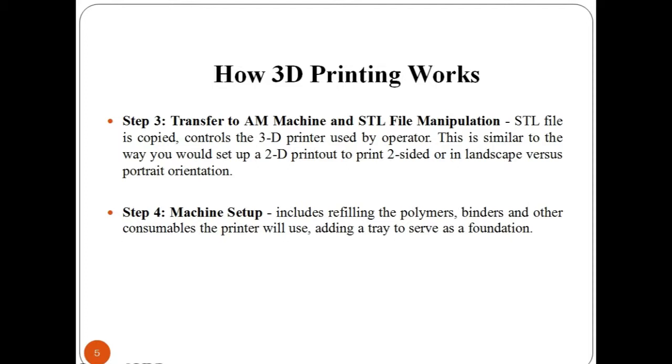For this, insert the part material and support material cartridge. The system will automatically feed the material filament to the extrusion head. Insert a base and close the chamber door. You are ready to build. Select your job from the queue and press the machine start button. The 3D printer heats the build chamber and brings the plastic liquefier up to operating temperature.